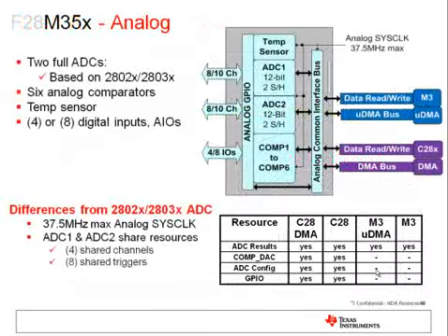The ADC is also very similar to Piccolo's ADC. It's a start of conversion based ADC, which allows for easy creation of conversion sequences that can be mapped to specific start of conversion triggers. Triggers can come from software, PWMs, GPIOs, or CPU timers. Again, Piccolo users today will find it very similar to switch to Concerto.